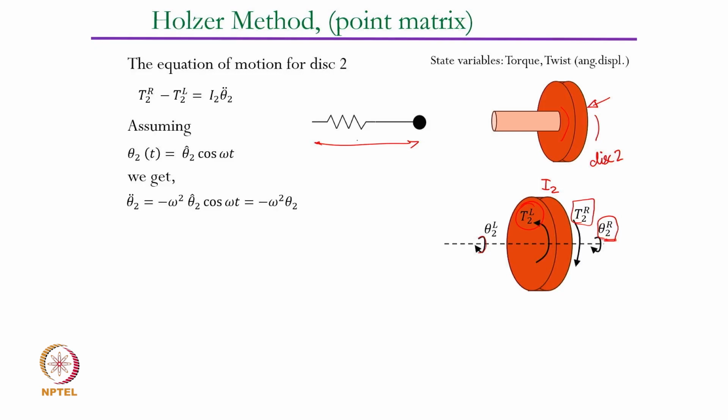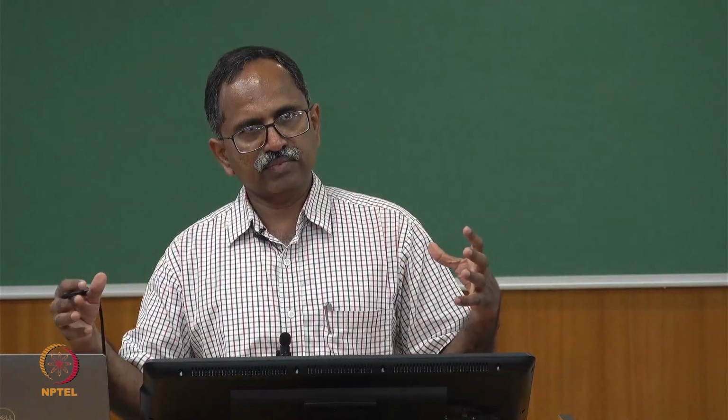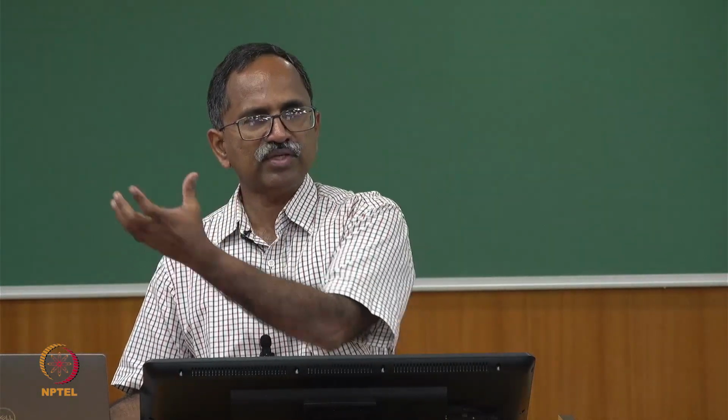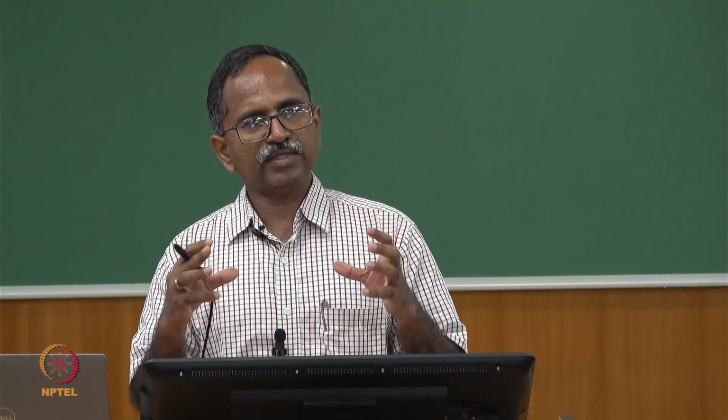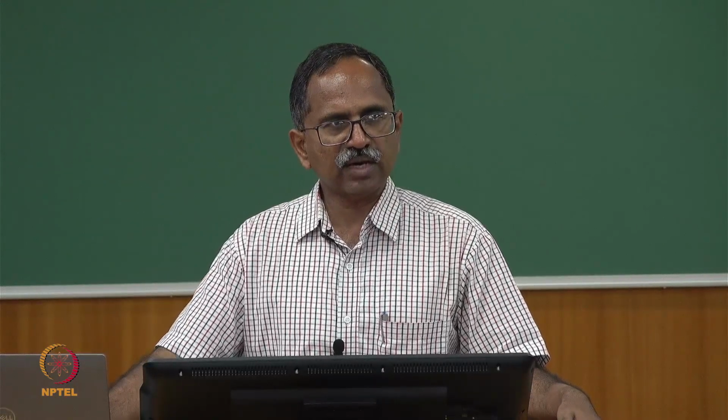Now when we say we are wanting to find out the eigenvalue, at any of the eigenvalue, the entire system, be it segment 1, segment 2, segment 3, segment n, all these segments are going to exhibit or go through a principal mode or normal mode of vibration, wherein all the elements are going to oscillate at the same natural frequency. It is not going to be like segment 1 vibrates with the first natural frequency, segment n vibrates with 10th natural frequency. It does not happen like that, right.